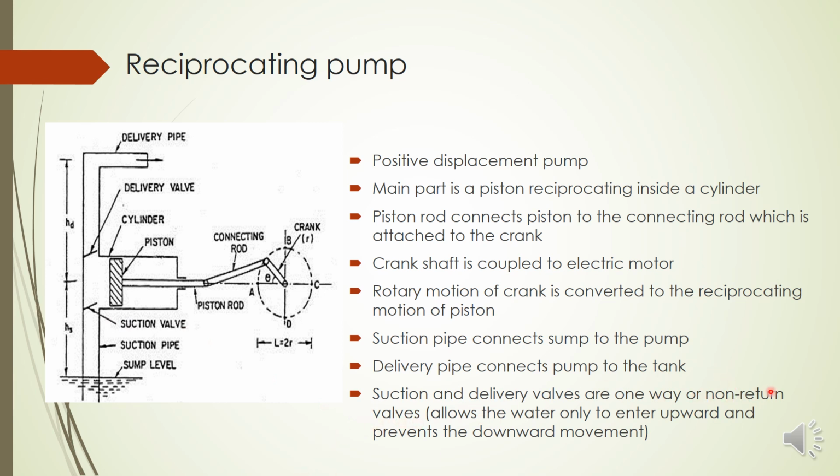So what do you mean by one-way valve? Yes, it can be opened and closed in only one direction. And here it is the upward direction. So this valve will open only in the upward direction, and it will not open in the downward direction, both these valves. So that is the importance of these valves. So these are the overall parts of a reciprocating pump.